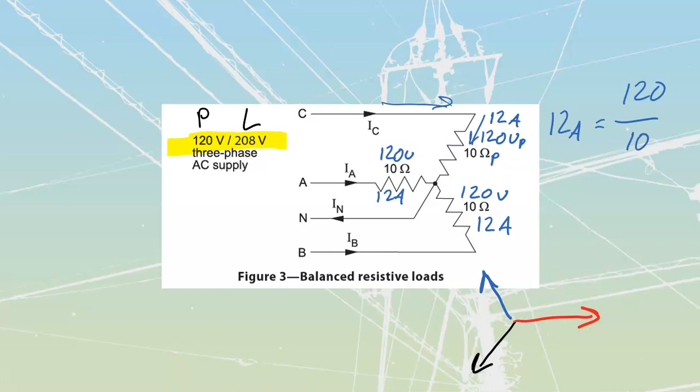And so I could just take those values and punch them into my calculator. We're just going to put this in as 120 angle 120. This one is going to be 120 angle 0, and then this one over here is going to be 120, and then you can do this one two ways. You can either do it as a negative angle, or you can do it as a positive angle. If you do it as a positive angle, it's going to be 240. It's 120 minus out of 360. You can do either one. I prefer to just keep everything positive so that I don't end up dropping any numbers on my calculator. We're just going to add all three of these together.